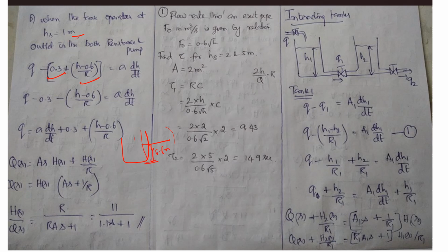So this whole thing is H. We have to subtract this. We don't need this because from here only this dynamics is actuated. So H minus 0.6. Okay. Then as usual, take the Laplace transform. So finally, we'll have this kind of transfer function.